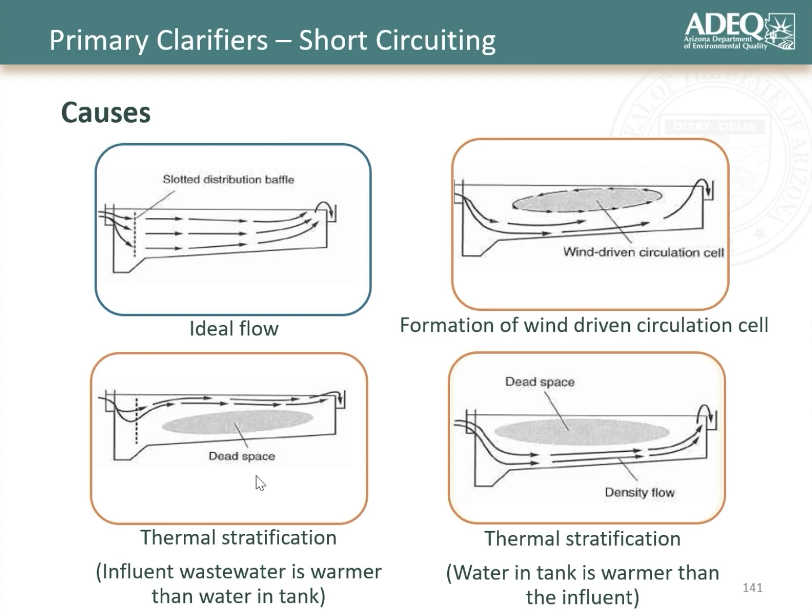And then effectively, there's space within your clarifier that is not active, a dead space. And so you have a shorter retention time as a result of that. Also, wind can cause circulation cells within your system that prevent the water from mixing with that too. So these are all things to consider and to evaluate as part of your treatment system.